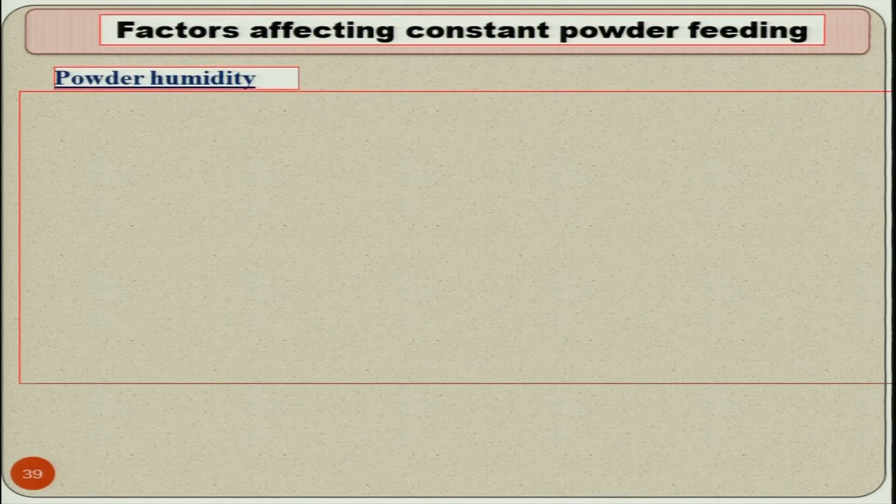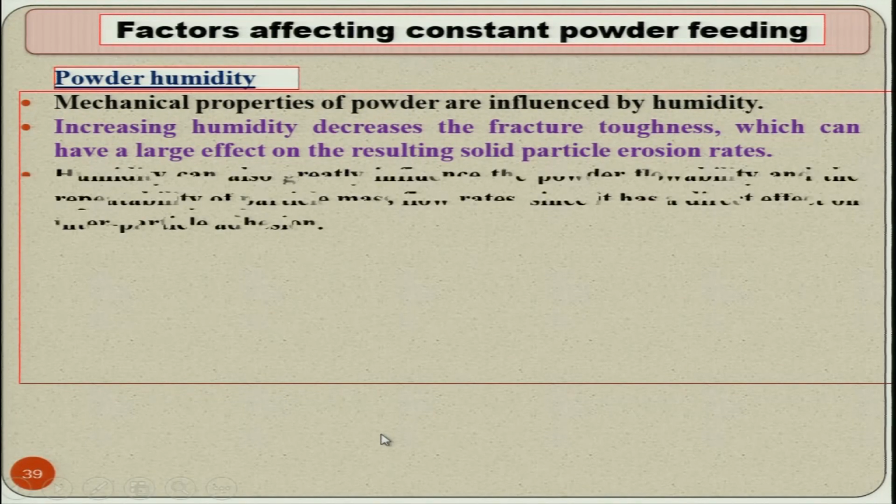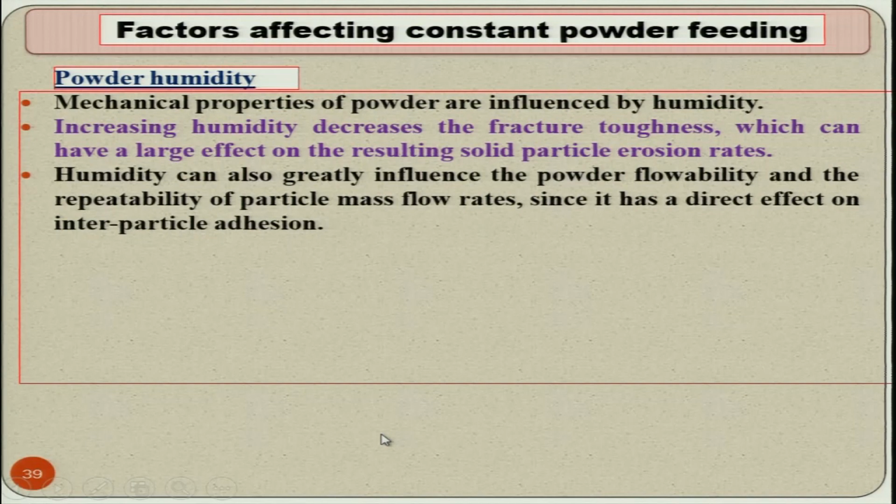Again, powder humidity is a very important aspect. Mechanical properties of powders are influenced to a large extent by the humidity. Hence, drying of the powder and drying of the air, both are very important. Increased humidity decreases the fracture toughness, which can have a large effect on resulting solid particle erosion rates. This is very important. So, powder as well as air both should be dried before they mix in the mixing